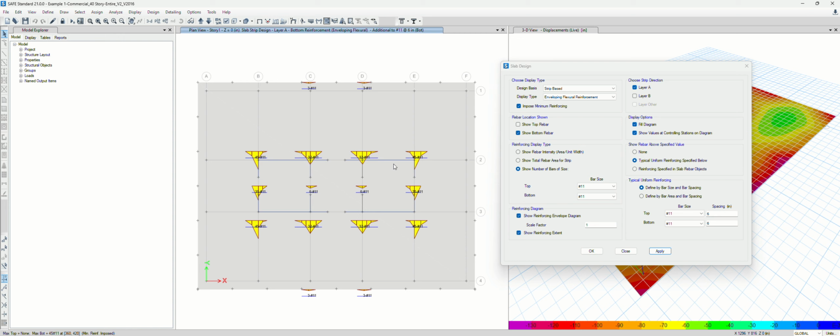In X, Y direction, I've been designing walls, probably 2 layers in each direction is pretty common, sometimes 3 layers bottom bar in X direction, another 3 layers in Y direction. Still, this thickness is very huge. We are talking about, right, the mat foundation, almost 96 inches for a 40-story building. Sometimes even much bigger, almost 10 feet or 11, 12 feet. Think about the 600-meter tall building. So we need to do some iterations, right?